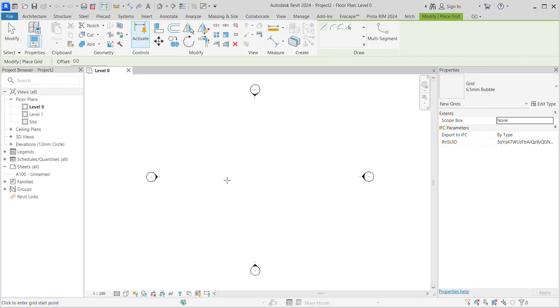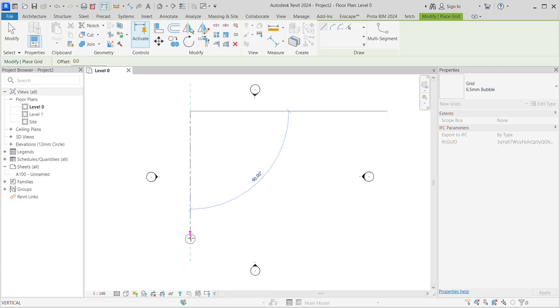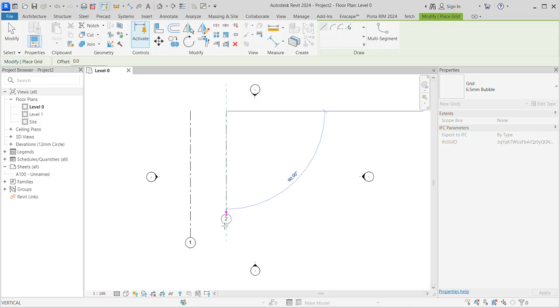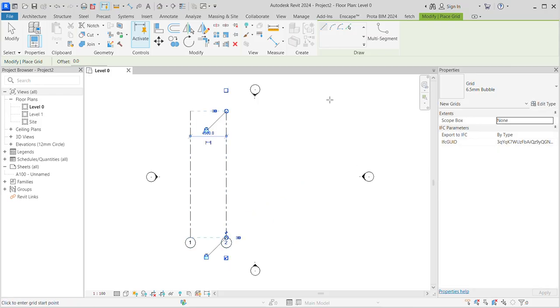So we want to draw specified distance intervals. Let's start with the vertical part. You draw the first one. The moment you click to align with the first one, you see it has given you the distance. Maybe you want 4,500, type 4,500, and you have it nicely.